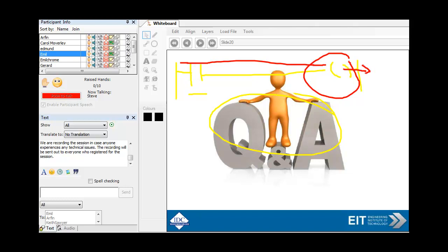So that's the coil, and often we have a thing called a sealing contact, which means as soon as this power flows through there, and that bit there is, say, number 1, and this bit's called number 1, then on the second scan coming through the PLC, this bit will be locked in as on, and the power flow will be there forever. So what we've got to do is put another thing there, which is your emergency push button stop, or a stop switch. That's really about it.